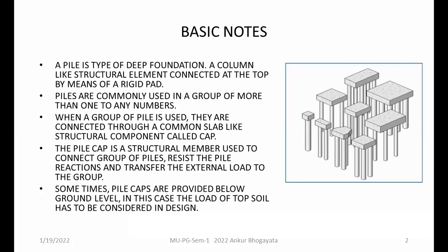And therefore, the depth of the pile cap is a very important component of the design, on which we should always focus, especially in case of the shear resisting capacity of the concrete that you are using. So it is to be understood, from the practical point of view, that normal concrete mix is not suitable for any sort of pile cap. At least you should practice with M25 and above, and with heavy reinforcement. So you are going to see some interesting images also in upcoming slides, which show the cage-like structure of the pile cap.